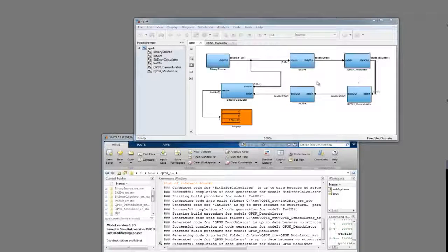So once I make sure the Simulink model is valid, the next thing I want to do is generate source code for these subsystems in Simulink. Embedded Coder allows me to generate the behavior for these blocks as C or C++ files. I'd like to take that generated code later and use it as the behavior for my SCA component. So I'll show you how to do that shortly.